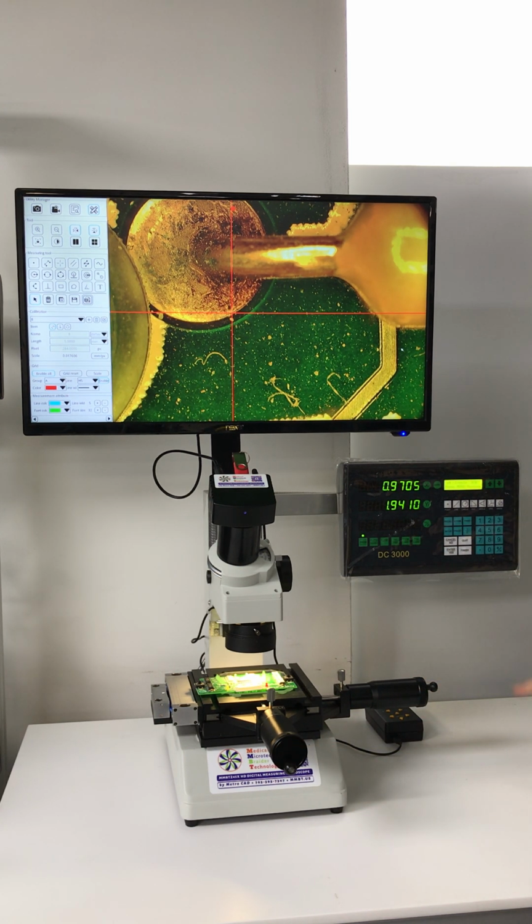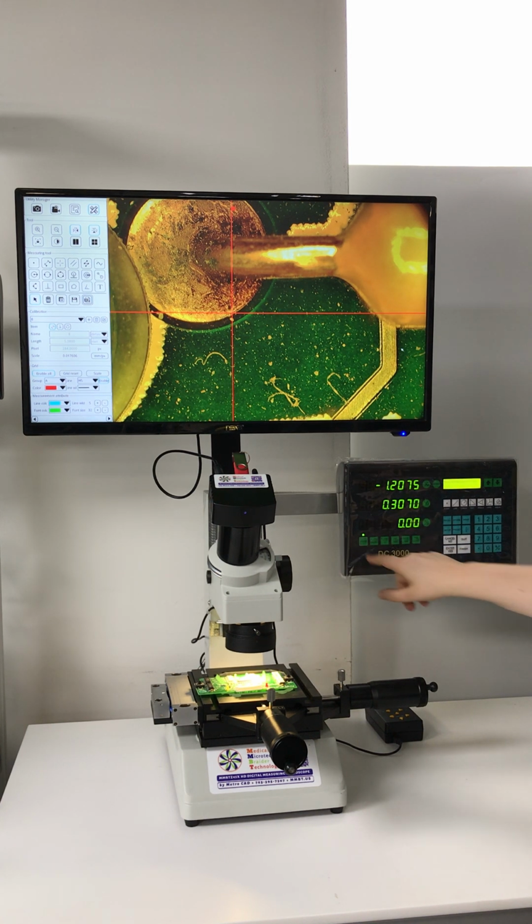Alright, so again, that'll have it. And again, when you see the program button highlighted, that is still programming. So press program again, press enter, and are you finished? Press enter. If I need to bring that one back up again, I'll press program, run program, program number is 1, and again you can save 10 programs with up to 100 steps. Press enter. So now my circle measurement with 6 points is all ready. So that's if you have presets that you always want to do.